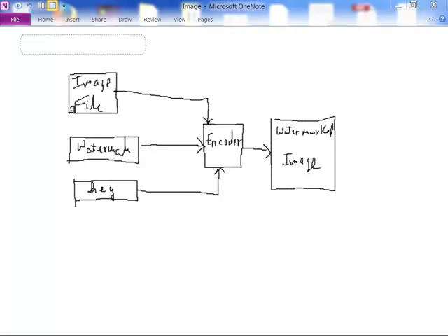To hide a signature, the designer would create an additional set of constraints, and these would be created using a secret key. They're selected in a way that they don't conflict with the constraints of the original problem. So we're not violating the actual design constraints of the intellectual property. We're just placing additional constraints onto the design that are derived from a secret key.